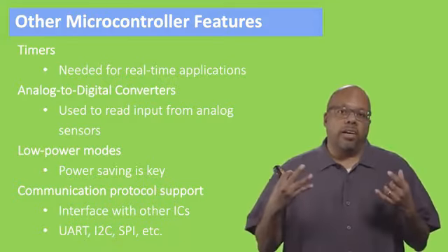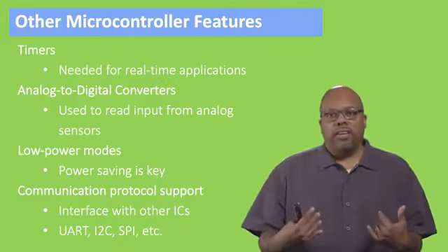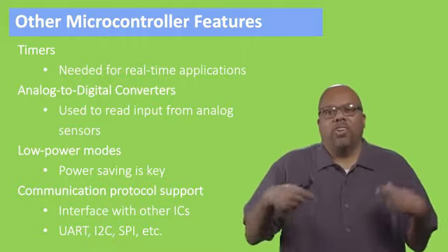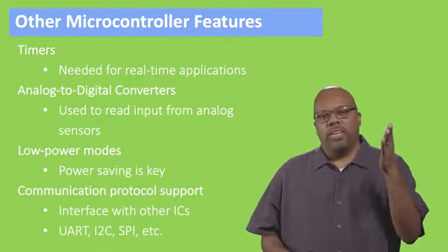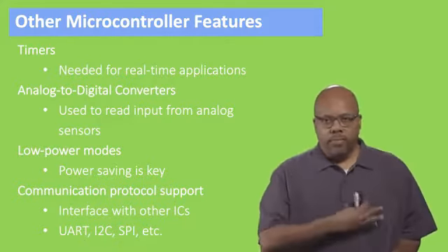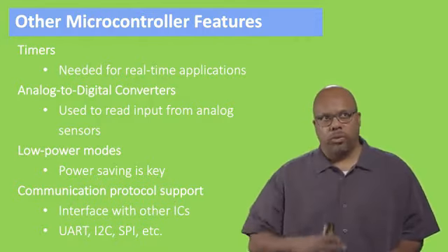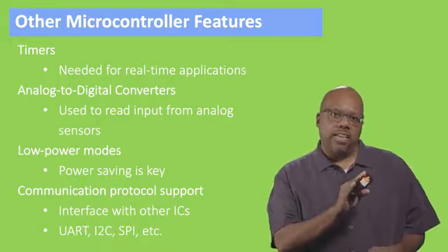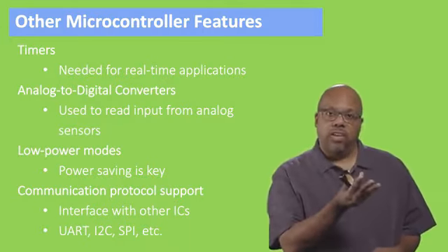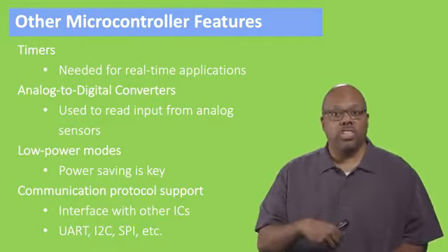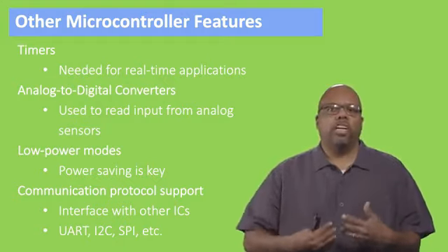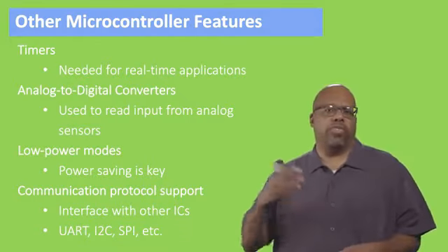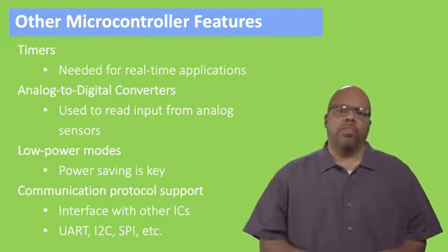So if you want an IoT device to process these analog phenomena, it has to convert it into a digital number. So the brightness of this light, say I want my IoT system to do something when the brightness reaches a certain threshold. It needs to be able to take that analog value of that light brightness, convert it to a digital number that I can use in my code. I can say if brightness is greater than 1,000 or some digital number, right?